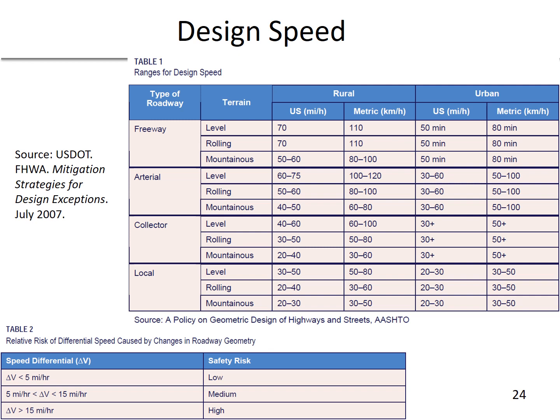The Green Book has design speed recommendations from 15 to 80 miles per hour in 5 mile per hour increments, so a lot of information is provided in the Green Book. And these are the maximum safe speeds under favorable conditions. In most locations, the design speed is about 5 or 10 miles per hour greater than the speed limit. And the design speed's particularly important for horizontal and vertical curvature.